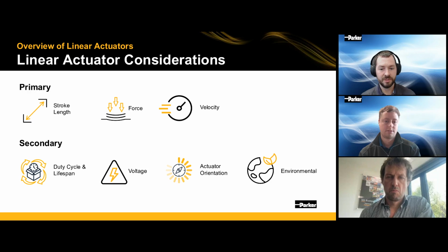Are we going to be looking at applications where salt or corrosion are a risk, or even submersion underwater? Making sure that the actuator is able to withstand those harsh environmental conditions that you'd see in a typical on or off highway application is really critical to make sure that you're getting the best bang for your buck out of your linear actuator technology.